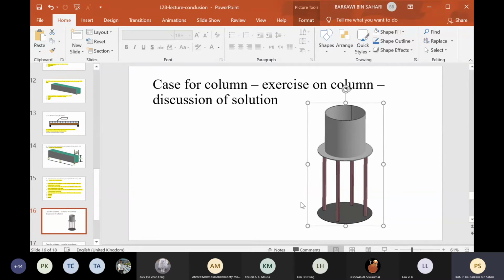So in this situation, I'm not going to write anything, just to explain what the problem requires. We have the external load, which is the weight of the tank, the weight of the liquid in the tank. So you have to calculate the weight of the liquid, because that's the design requirement. The liquid should be filled up in this particular tank of this particular size. So it has its weight, to be supported. Now, 1/4 of this weight is to be supported by 1 column. One column will support 1/4 of the weight.